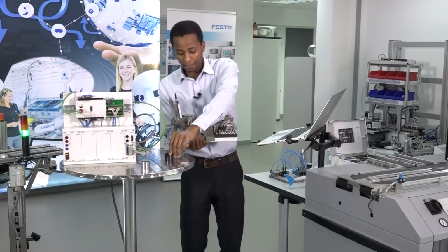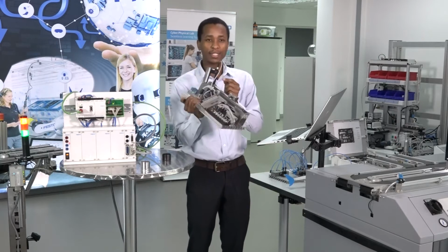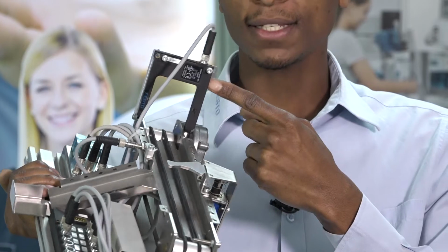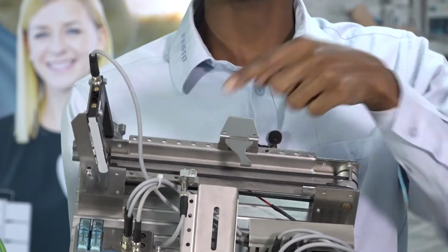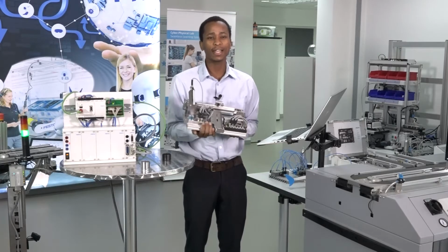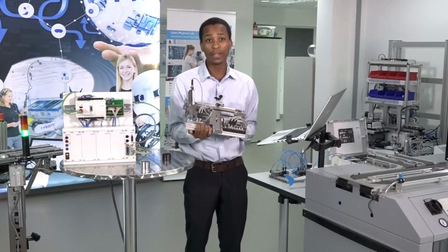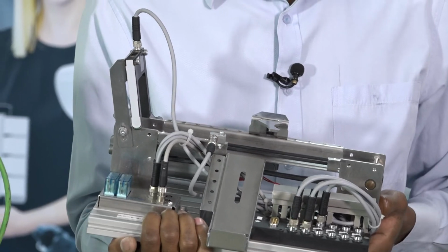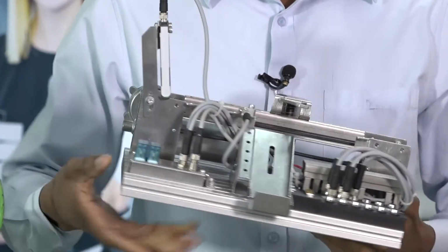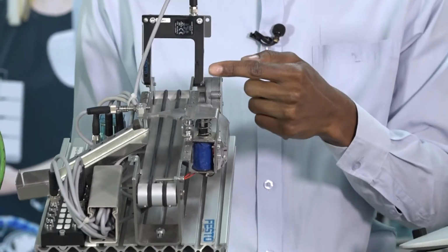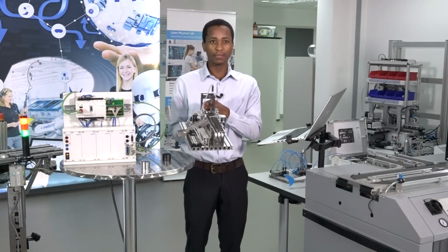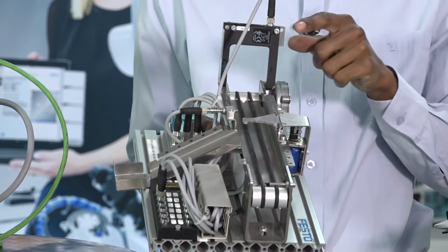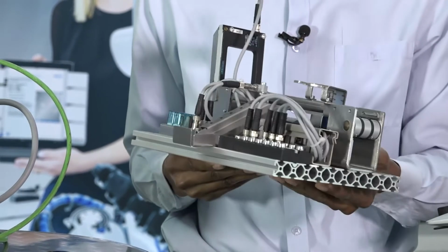Okay. And there's also different sensors. So we have an optical sensor. This is the one here. There is also an inductive sensor, which is this one over here. What the inductive sensor does is it detects any metallic parts that are passing through the conveyor, while the optical sensor uses a transmitter and receiver. So there's a transmitter and a receiver here. Light is transmitted here and it's received there, so that if there's any object in between, it blocks the light beam, and so this is where we get the signal from the sensor.